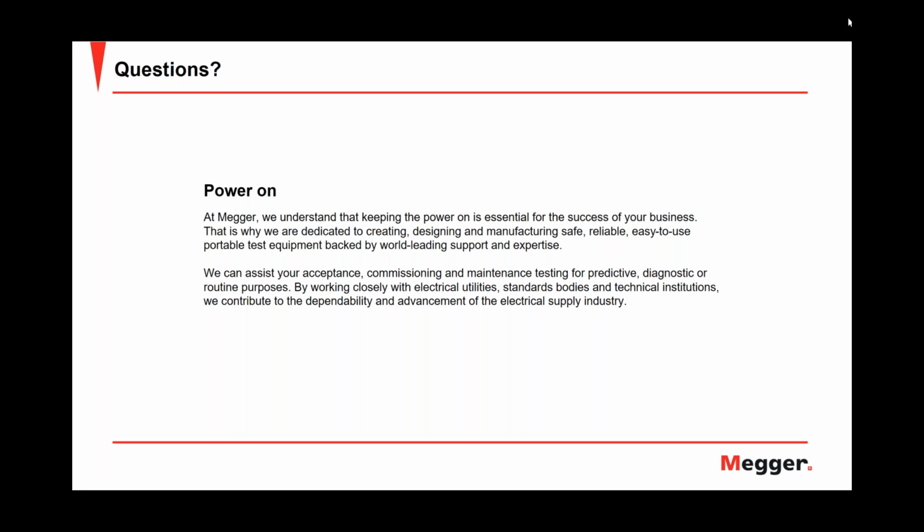Well, more overall, I think it's fair to say the more effective cable test is an AC test, simply because you have changing polarity. That change in polarity happens at such a fast rate, like 8 milliseconds or whatever, that it puts a lot of stress on the cable. It's not just the voltage stress, it's also the change in the voltage over time that stresses the cable quite a bit.